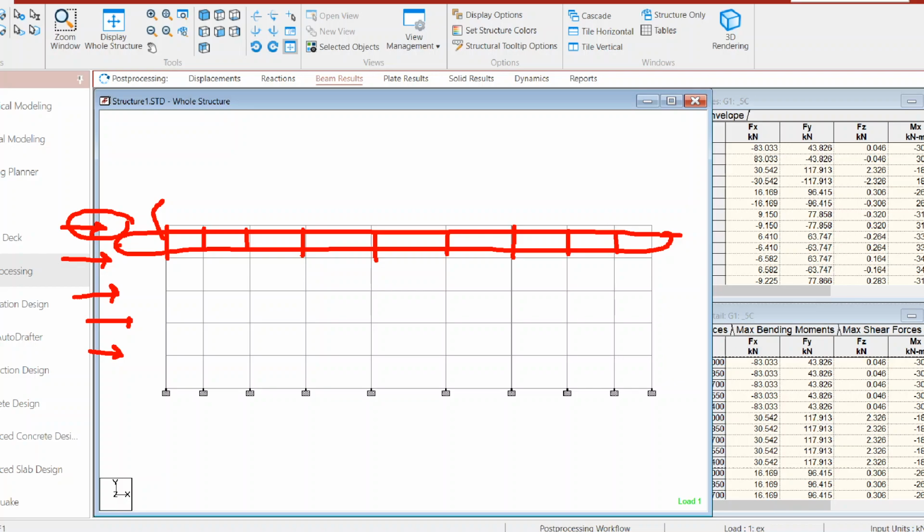So therefore, to verify the shear, to determine the shear on this floor, we will sum up all the shear in our columns. Okay, because columns are the only members that will resist the lateral, the earthquake force. We don't have shear walls here, so we only have columns. Of course, due to frame sway, the girders will also be resisting that sway. Okay, so that's what you need to do.